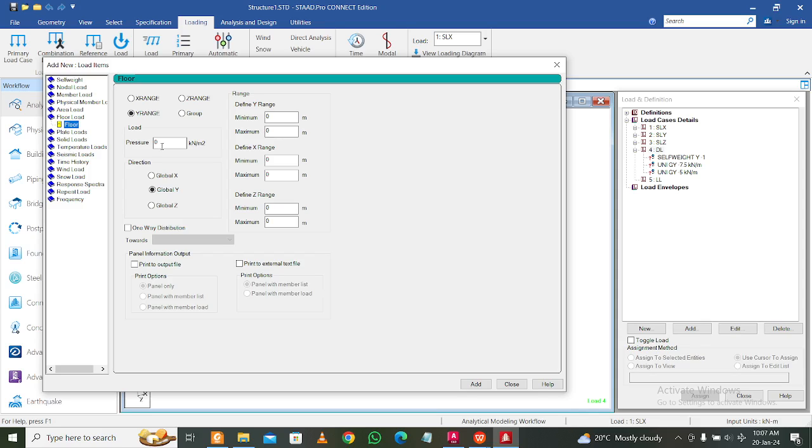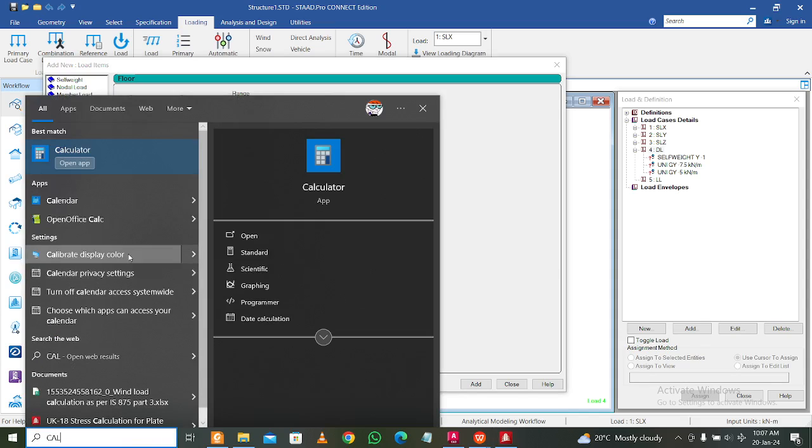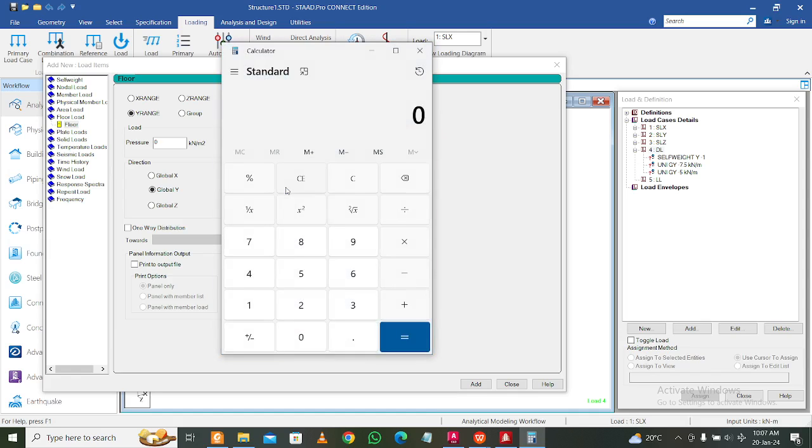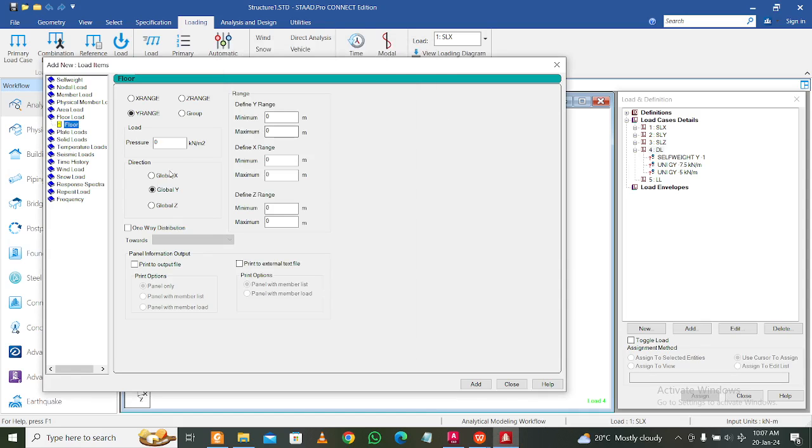And also we need to add the slab load, because you have not applied any slabs here. Consider 125 mm slabs here. So 0.125 into 25, which is the unit weight of concrete, and it will be 3.125. So 3.125 plus 2, it will be 5.125 along with the floor finish and this. Okay, so let's do here